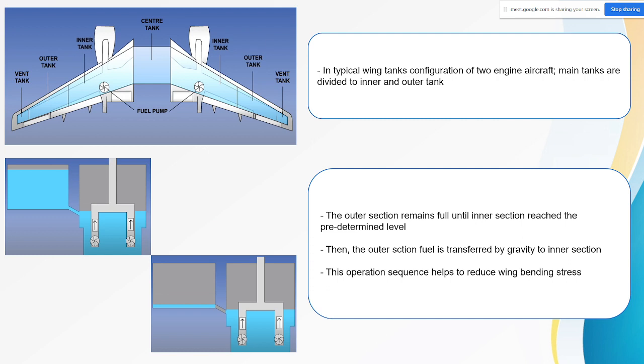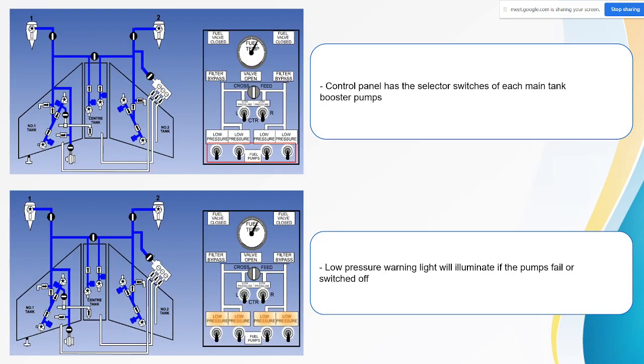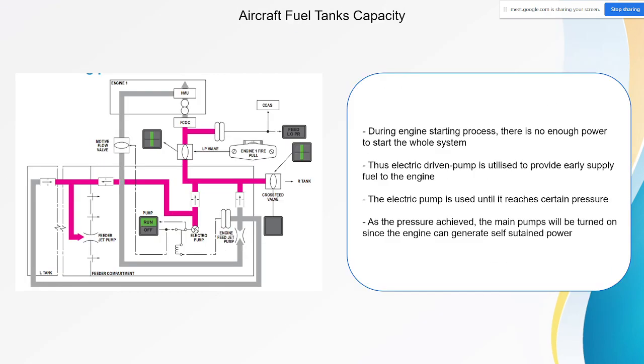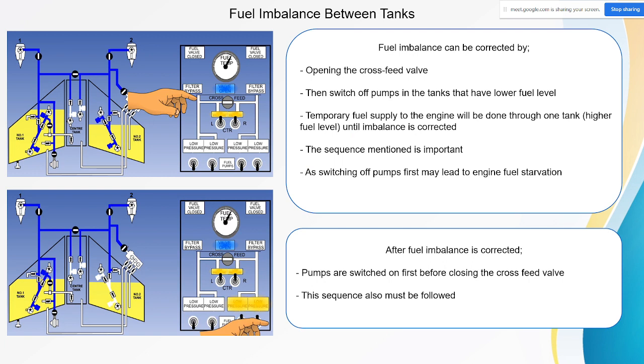Sorry, just now I have a bad internet connection, but I have a question regarding the fuel imbalance just now. When supposedly to do the fuel imbalance correction, is it during flight? Yeah, during flight, because fuel imbalance can occur during flight. Difference in consumption may occur during flight because the engine is running.